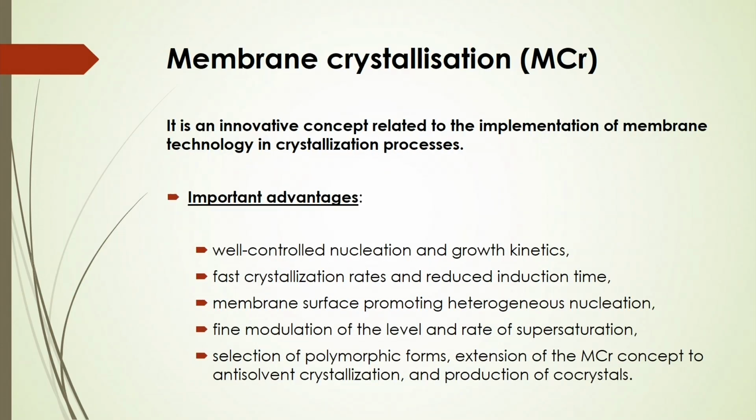And membrane crystallization is also another aspect of using membrane for process intensification. It is an innovative concept related to the implementation of membrane technology in crystallization processes. It is important because of well controlled nucleation and growth kinetics, fast crystallization is possible, and also you can reduce the induction time, and fine modulation of the level and rate of supersaturation is possible.